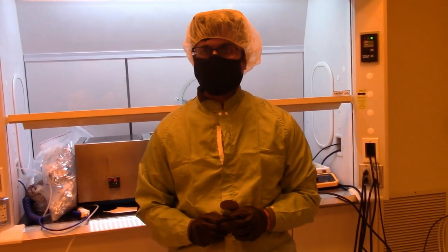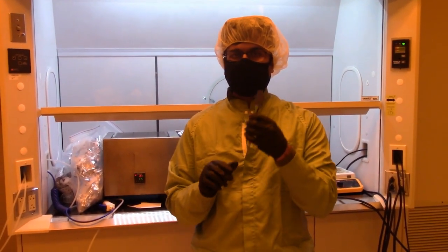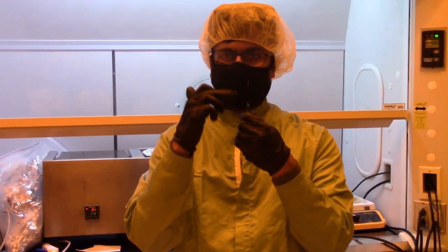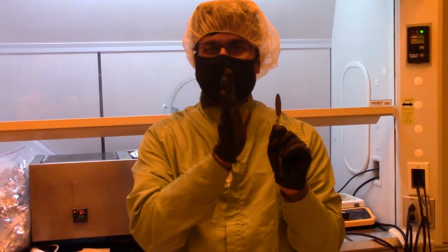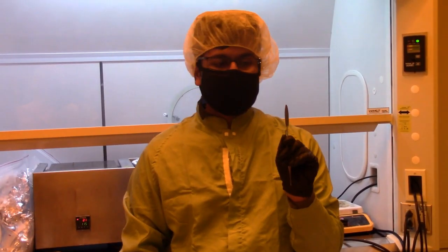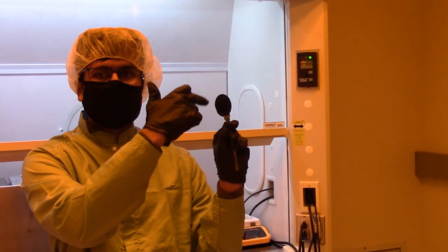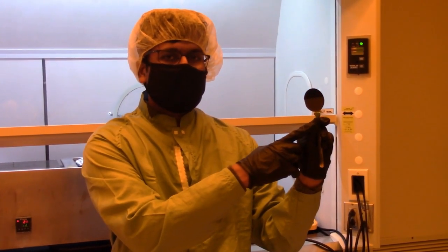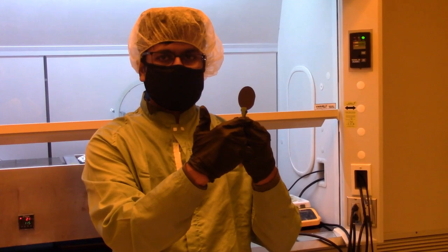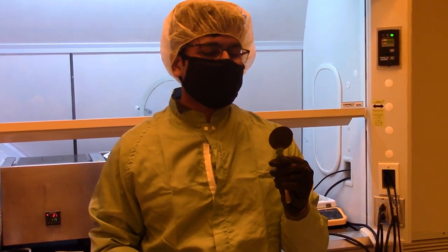Now that we have measured the thickness of the oxide, we can go ahead with the next steps, which involve removing the oxide on the back side of the wafer to make a metal contact. The metal oxide semiconductor contact needs to be on the shiny surface, so it is important to protect the oxide on the top side, or shiny side, of the wafer, whereas we remove the oxide on the back side of the wafer, which is grown during the oxidation step.